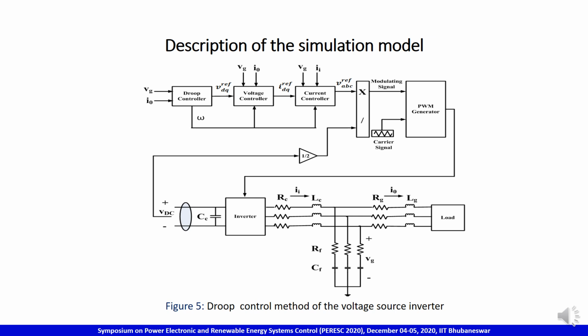This final reference voltage generated by the current controller, which has to be followed by the inverter, is used to generate the pulses using the sinusoidal pulse width modulation technique, and these pulses are fed to the gate drives of the inverter.